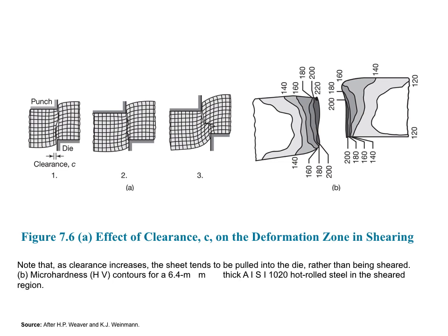Another important thing to remember is the distance the punch travels depends upon the maximum shear strain of the material prior to fracture and separation. Therefore, brittle and cold worked parts require little travel to complete shearing.